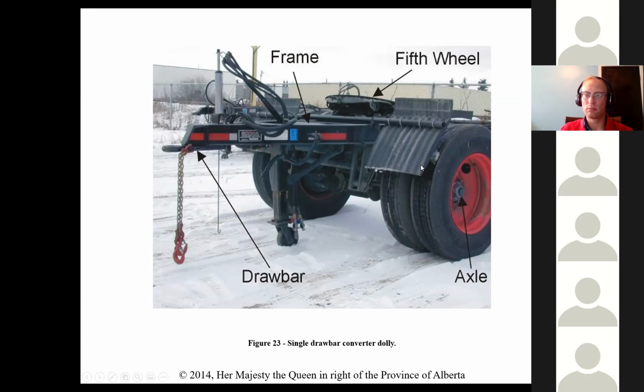Rosano had a tandem axle converter, and one axle was pilot mount and the other axle was demountable, like Dayton wheels. Yep, I've seen things like that before too. And as long as it's the same on each axle, it should be okay. And it's about weight rating as well. If it's within the weight range and they're rated for the correct size, I mean, the wheel end on there, as long as it's by each axle and the braking force is equal, it should be good.